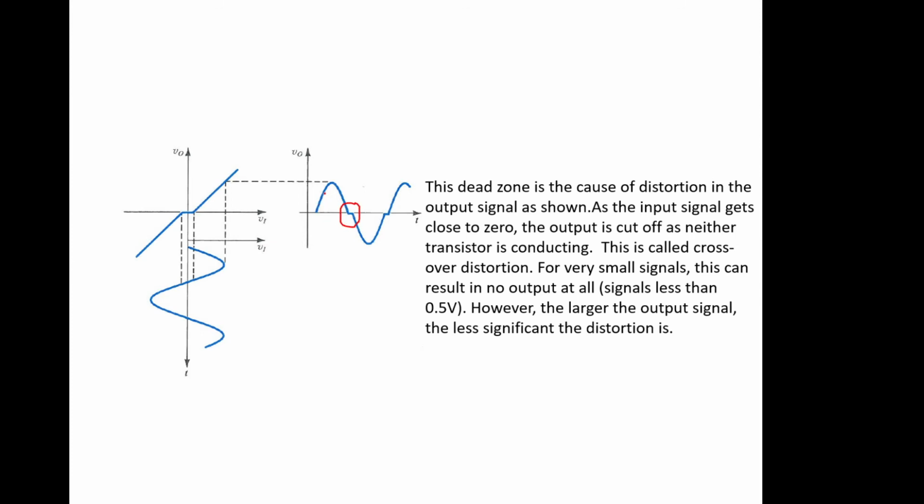And if you did an FFT of this, or a Fourier transform, or just measured the spectrum, if this sine wave is say 1 kilohertz, you'd get a 1 kilohertz spike, and then because we've got very sharp corners here, we'd end up with some harmonics appearing higher up, and then we're starting to get distortion, because ideally we wouldn't want harmonics, we just want the pure sine wave because that's what we're putting in, but we're generating some harmonics.